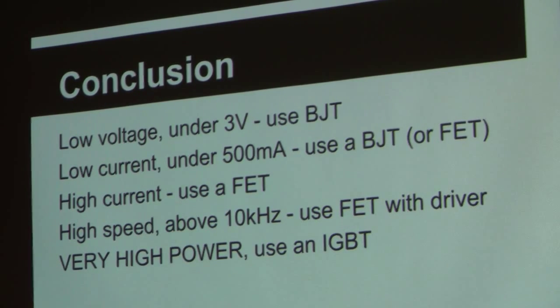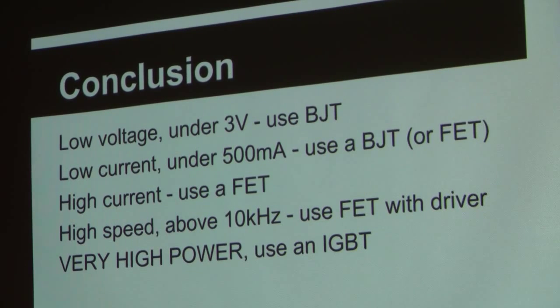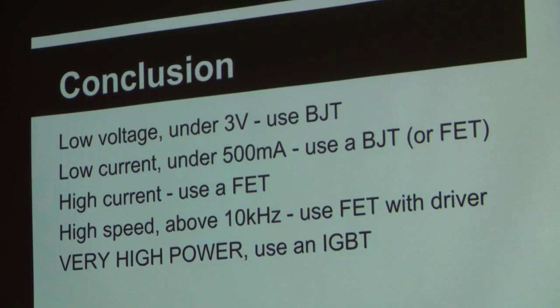And for the insane, who want to work in the high-power physics, doing pulse demonstration of magnetic stuff, IGBTs are the insulated gate bipolar junction transistors, which are a little bit like BJTs and a little bit like MOSFETs. That's where those thrive. If you know somebody who says, well, I'd like to switch this 3,000 volt source at 200 amps at 250 kilohertz, you want IGBTs. That's what they live at. So that's next week's class.